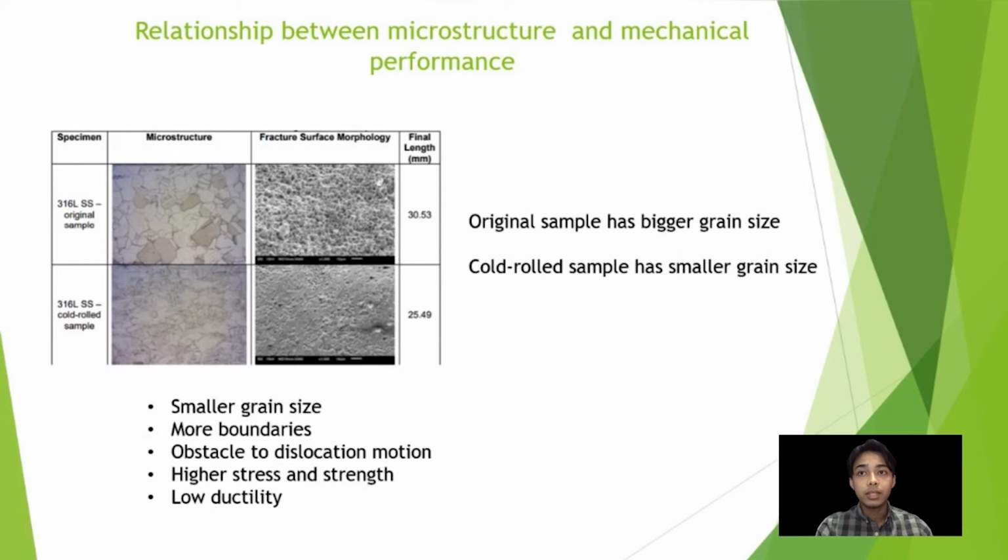Mechanical performance is also used to help classify and identify material. The most common properties considered are strength, ductility, hardness, impact resistance, and fracture toughness. Most structural materials are anisotropic, which means that their material properties vary with orientation. The smaller grain size will make more boundaries exist. When more boundaries exist, there are more obstacles to dislocation motion. This condition will make the material higher in strength and toughness, but the ductility will decrease as the strength increases.